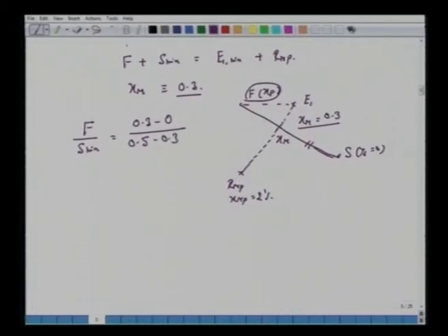So the idea was, how did you get this? Instead of working on this del min point, we have calculated S min based on this mixing rule. In the previous example, recall, we located this del min, but in that problem we could not find out S, because in the earlier example we knew the amount of RNP raffinate, but in this case RNP is not given to us.